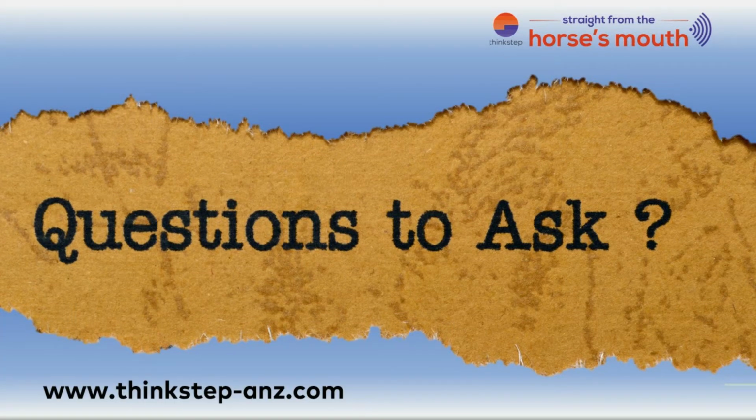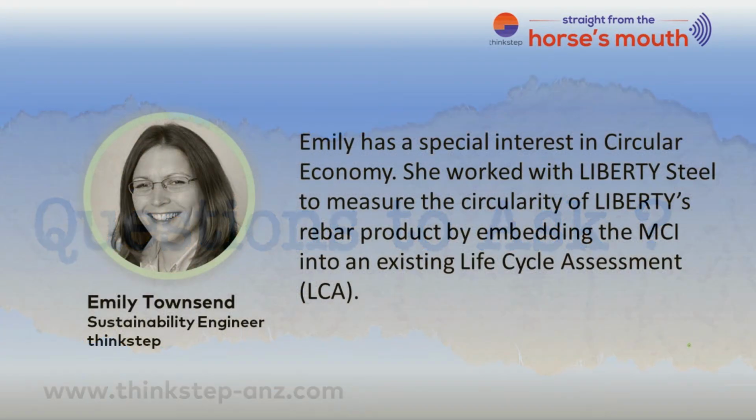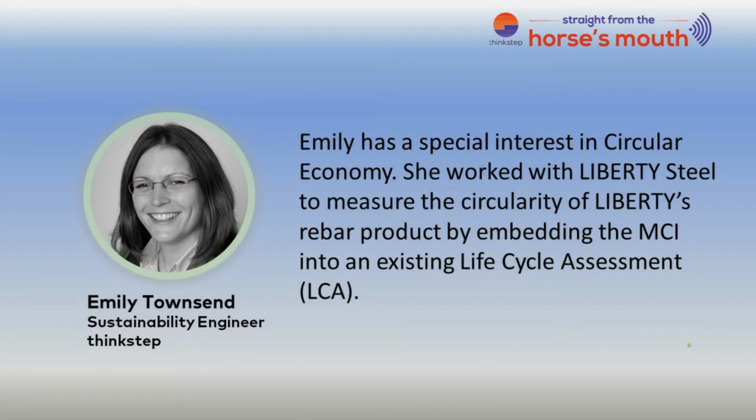Okay, so from Peter, do I have to do an EPD or LCA to calculate the Material Circularity Indicator? Peter, no, you don't. It's entirely possible to calculate it separate to an EPD or an LCA using a spreadsheet, for instance. One of the reasons that we suggest tying it in is because, as I mentioned, it really only tells you one thing about a product.